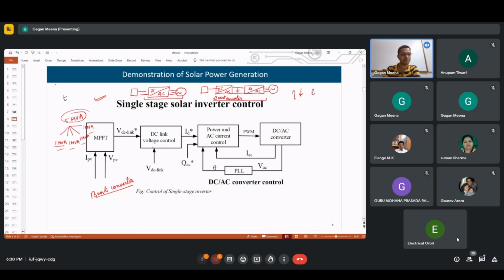In this case study, the IGBT stack which has been used, that inverter, has 4 legs. So this is one IGBT module which has 2 switches. 4 such modules are used, so we have 4 legs. With 4 legs, a 3 phase system would become 4 wire. But in the example only 3 phase has been considered, a 3 phase 3 wire system. So one leg is not used for that. There are only 3 phases.